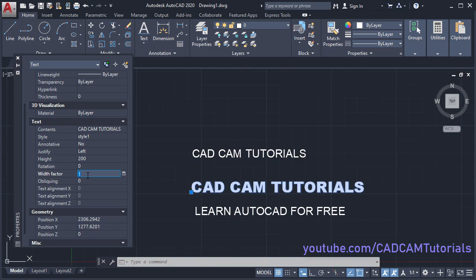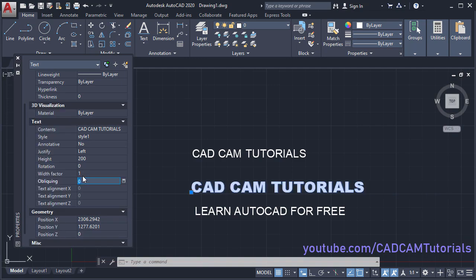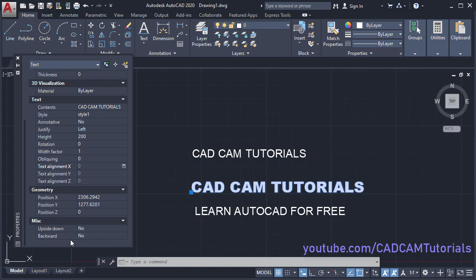Then width factor will change length. Suppose if I make it 0.5, it will be compressed. If I make it 2, it will be stretched. Standard value is 1, enter. Then if you want to make it italic, then you can specify your obliquing angle and enter. Suppose 0, enter. Then it is showing position, and from here you can make it upside down.